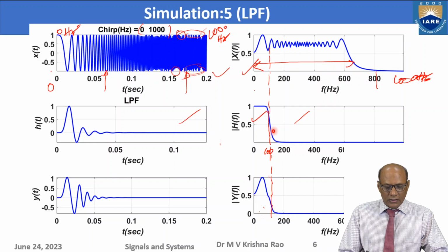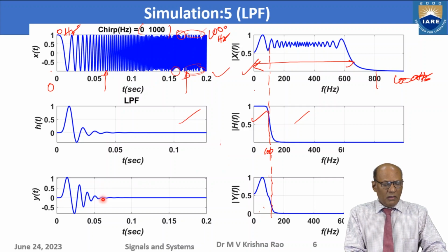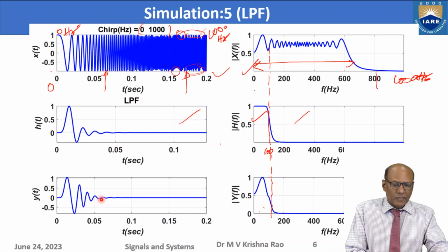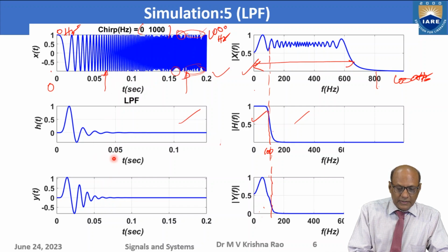Okay, so this spectrum corresponds to the output signal like this. So here basically this is low pass, this is wide band, I mean many frequencies, and when I convolve these two, see, this is some convolution, no? So this portion is 0. Because these are all time functions, this is a time function and this is also a time function. So I am convolving these two. So most of the time it is 0. So that 0 will reflect here in the output.